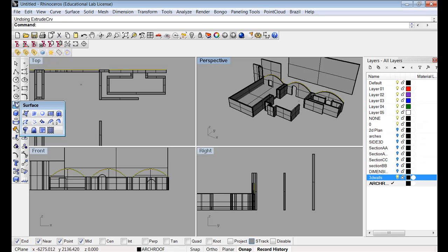The best example is if we went to 3D print a solid, we can, because it's actually got a thickness, whereas a surface is in the software, we can see it, yeah, but it's actually zero. So it's like a skin, but it's got actually no thickness. So if you try and print it, it's useless. If you want to 3D print a surface, you have to add a thickness to it, which you can do in Rhino.